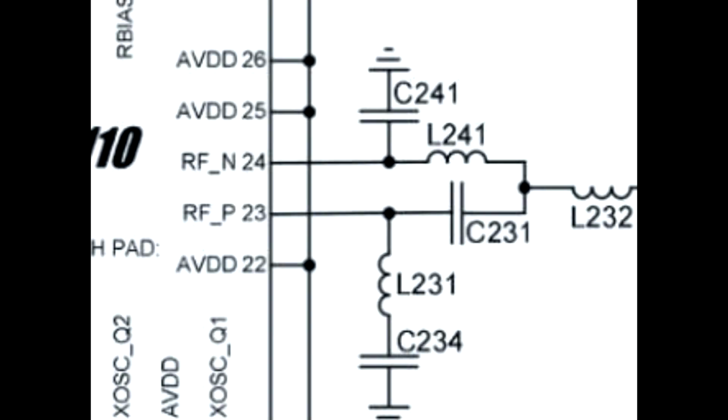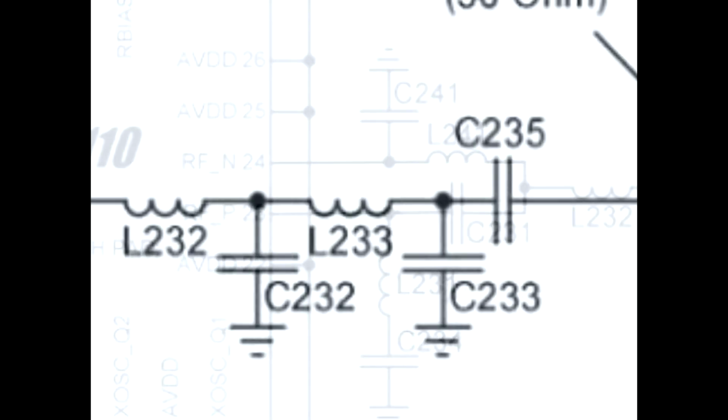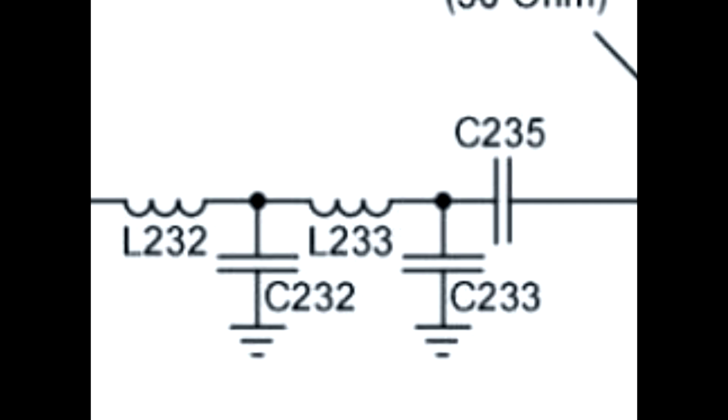An antenna is typically a single-ended signal, and transmission lines that we use across our PCBs most of the time are single-ended signals, and that's what I recommend you use, 50 ohm single-ended signals. So this balun converts us to a single-ended signal, and this filter probably also transforms the impedance, and we end up with a 50 ohm interface. Now, this is the most complicated part, and the manufacturer tells you exactly how to do it.